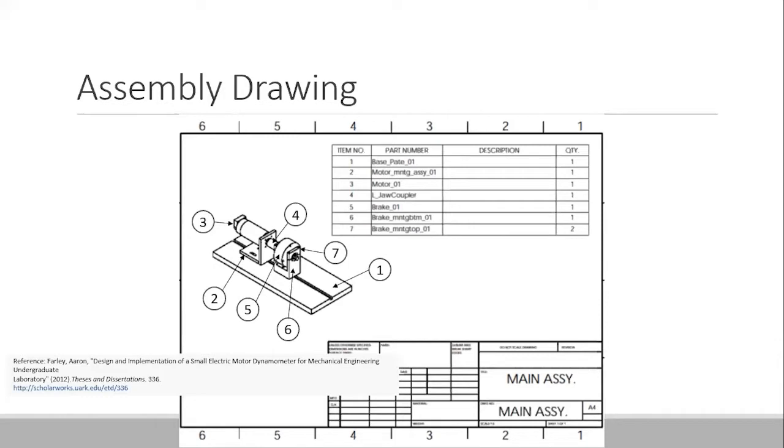So the purpose of the sub-assembly is that once you have fabricated the parts or procured the parts, how are you going to do the assembly? What is the sequence of assembly to be followed by a person so that you can get the top level assembly, or you can basically assemble the whole design. So the purpose of the sub-assembly drawings is to make sure that you have provided enough information in the drawing that will help the reader to assemble the parts or disassemble the parts easily. So the drawings should be prepared with that intent in mind.